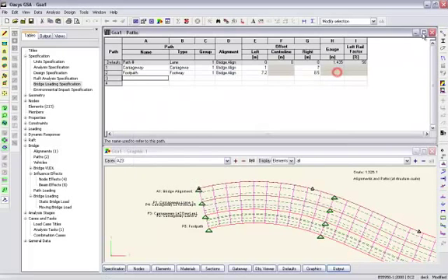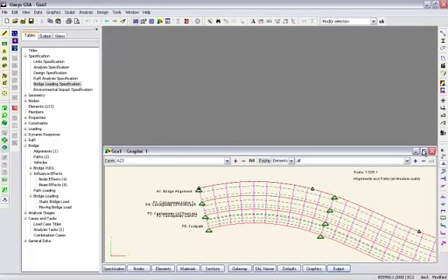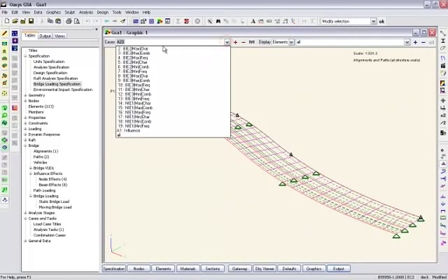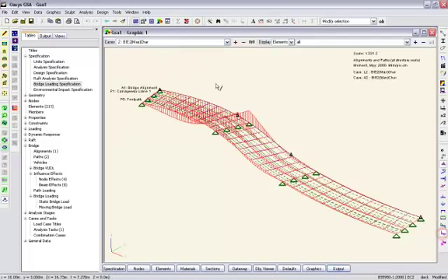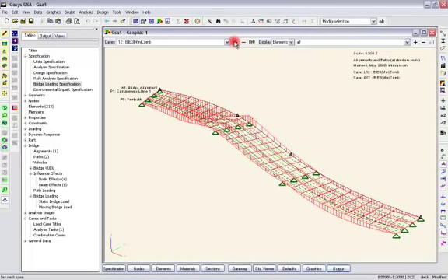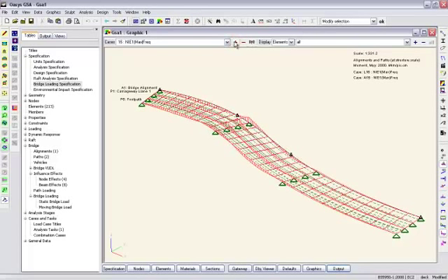Wonderful, it's finished. Let's look at our results. So we have all the various bending moments as before, which we can then envelope just like we did with the previous load case. And of course, being Eurocodes, you need to apply partial factors and combine them with a dead load, etc, etc, etc.